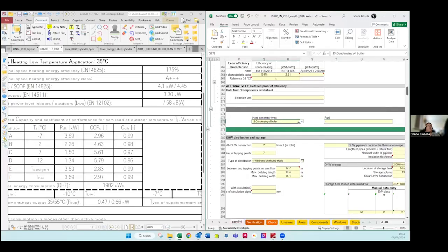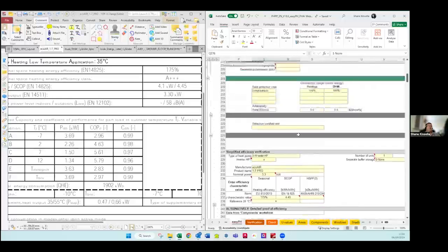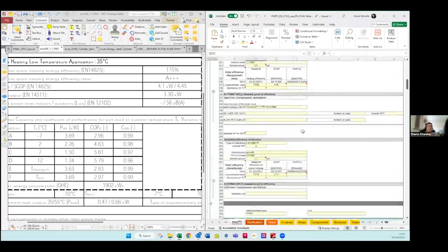So depending on your type of boiler, you will select your heat source to suit from there. So again, back up the top here, you can assign a heating boiler here and assign the percentage where you have a hybrid arrangement. Wouldn't be unusual to see hybrid arrangements in dwellings. So if that arises, you can model that there quite easily.